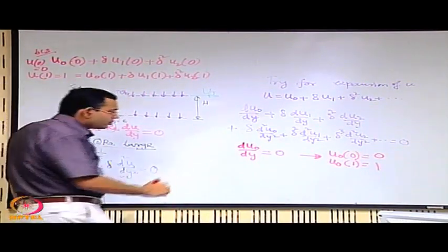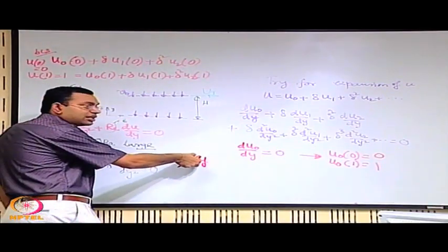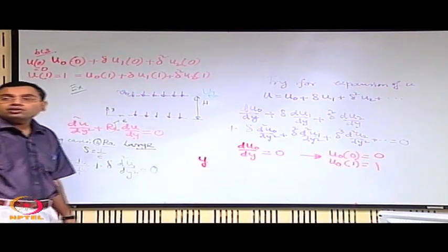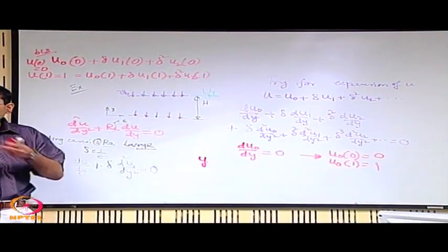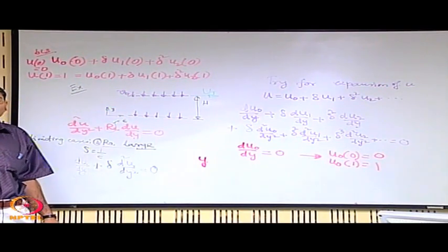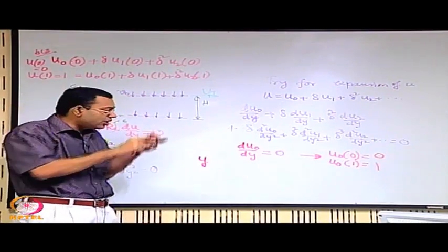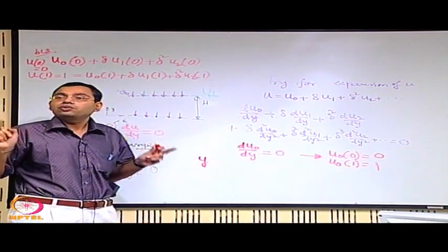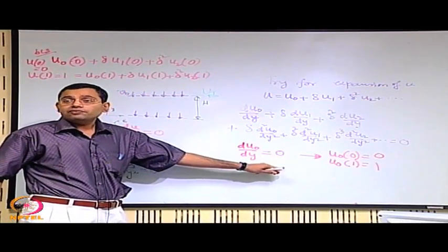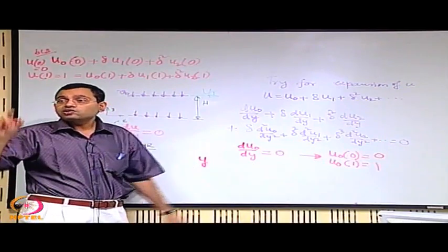So then within the boundary layer, if the transverse coordinate is y, you have to apply a magnification factor to the coordinate, so that it becomes large enough, blown up in proportion. Although it is thin, if you resolve it properly, it has to be given due importance. That is what we have mathematically recognized. Now we are trying to see physically how we can give it its due importance, only by resolving it properly.